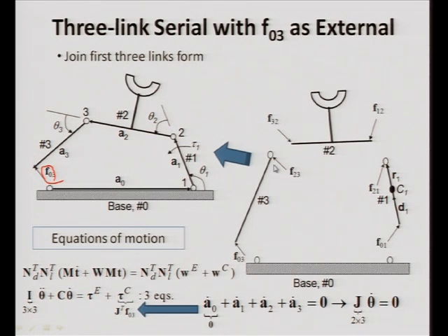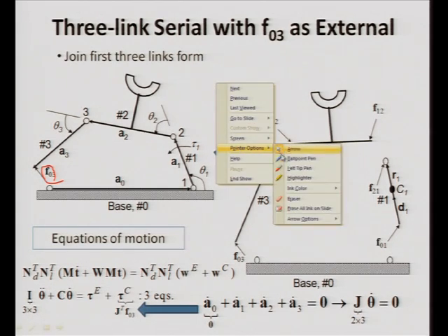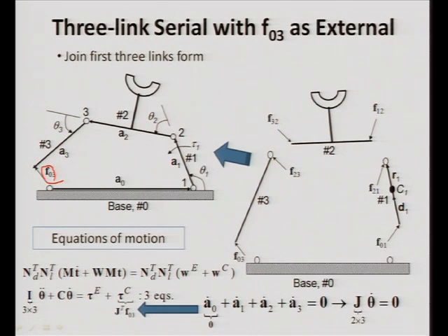If you treat it as a 3 dimensional object, then the reaction moments in the other directions will come. So, to make a uniform development, for the time being, let us treat all of them as special motions, and my dynamic constraints will take care of all these constraints to bring it to the final equation of motion. What we have learned in our serial chain system is that if you pre-multiply by N D transpose N L transpose, you will get the final equation of motion.